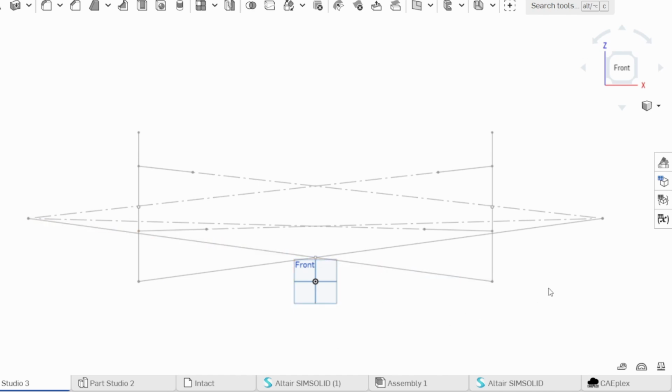So what is jacking force? We'll go back to our sketch. We have our wheel here, we'll call our outside wheel or outside tire. And there will be a lateral component of force that the tire is creating. That lateral component has to be reacted, and it's reacted by the A-arms. So there's a lateral component of the A-arms that is reacting the lateral component of the tire force. Since the A-arms are at an angle, there's going to be not only a lateral component, but also a vertical component of the A-arm force. So the vertical component is the jacking force.